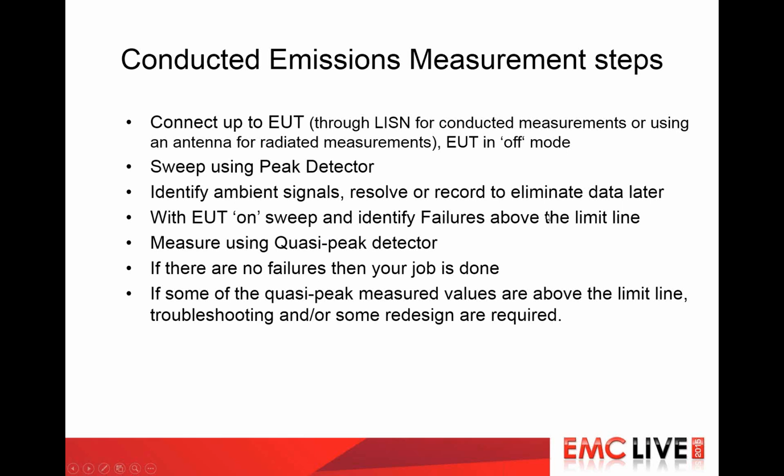You can identify what's the ambient noise, the background noise, versus what comes from your device. Then you can use a quasi-peak detector to measure your device. If there's no failures, your job's done, which doesn't usually happen. Then you have to go in and start doing some troubleshooting. And we'll have a slide that talks about that.